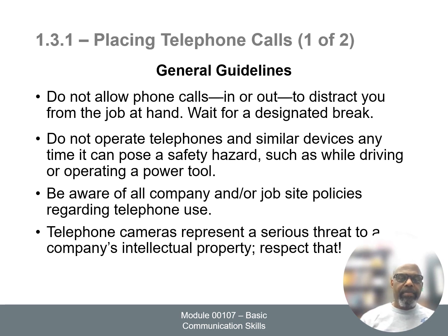Wait for a designated break to make those return phone calls. Do not operate telephones or similar devices anytime. It can pose a safety hazard. So in other words, you're on a crane. Only if you're using a phone on a crane, you should be talking to that crane operator. That's it. Nobody else. It can be very dangerous if that happened.